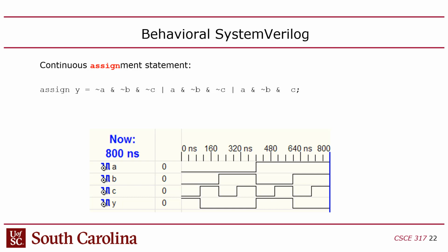You have to get used to reading these, and as you would imagine, that's the reason why we started this course out with SPI and I²C, because of course that was all about reading timing diagrams. But whenever you do hardware design, it's all timing diagrams, because that's really the only way to conceptualize the behavior of the logic, is through time. Some people use a list, which basically creates like a spreadsheet where every row is whenever a signal changes. That's kind of like what we gave you in Lab 1, actually, when you looked at those trace files. So you could look at a trace file, but usually in software you see it as this timing diagram.